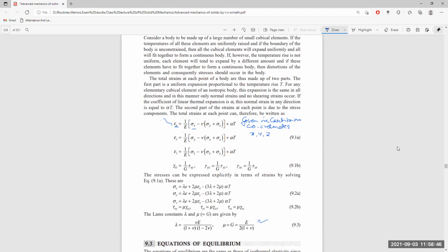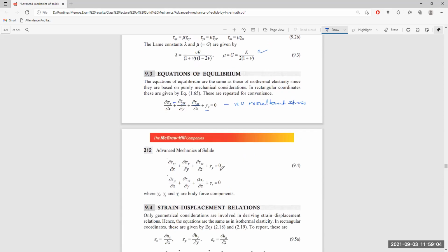Now in polar coordinates, it is not available in the z direction or longitudinal direction. We only replace epsilon x by epsilon r and epsilon y by epsilon theta itself. Meaning strain along the radial direction as well as the circumferential direction, and no strain along the longitudinal direction.